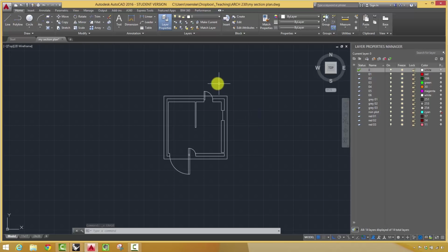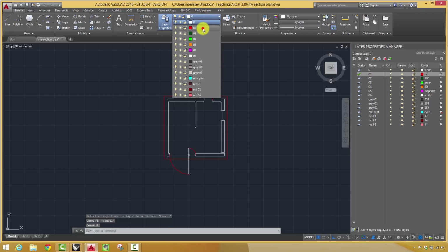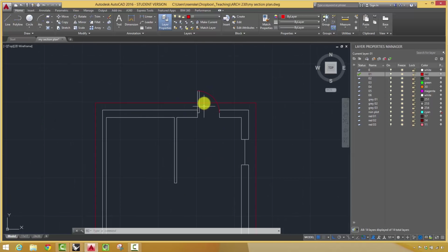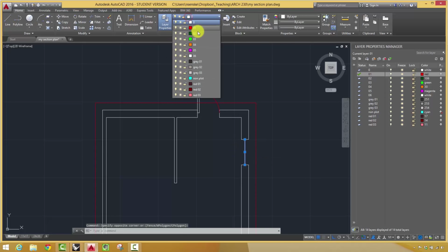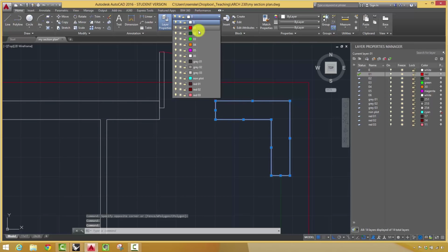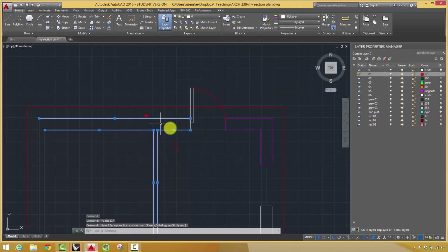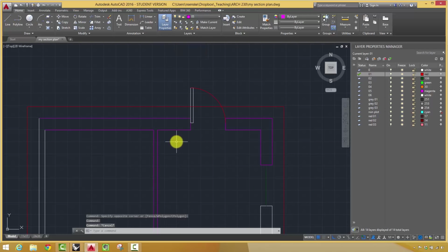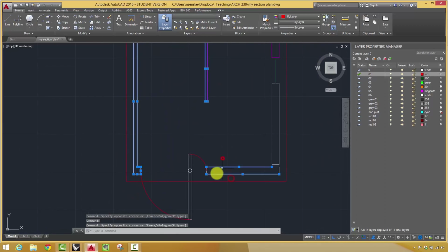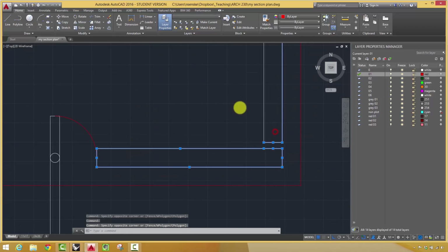So at this point, if I finish the drawing, I would start adjusting the hierarchy of the drawing. I think these are swings. This overhead piece is also a red. The window itself is going to be a 2. Remember, walls in a plan are typically these purples. And these aren't hard and fast rules, but I think they are easy to read with our template.